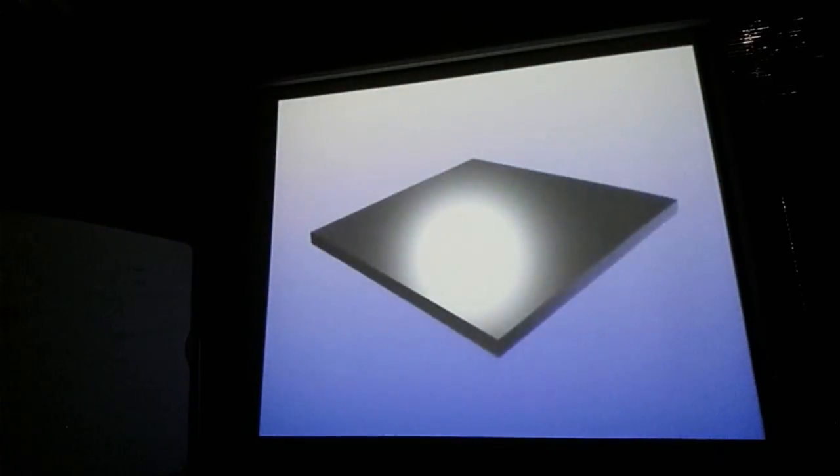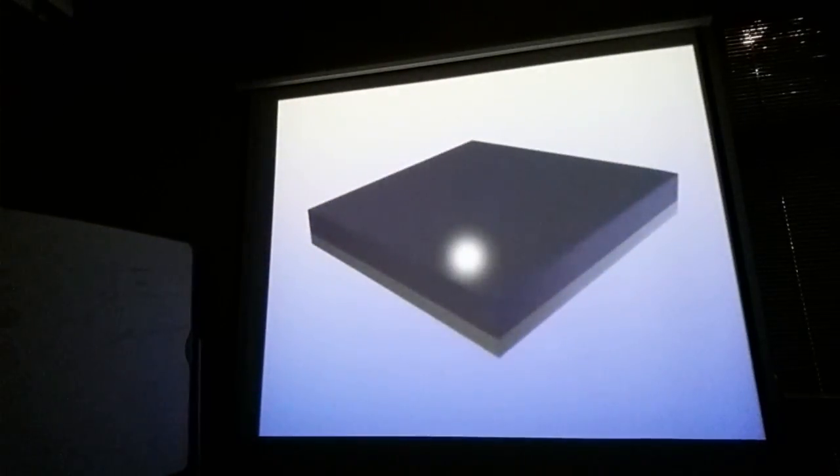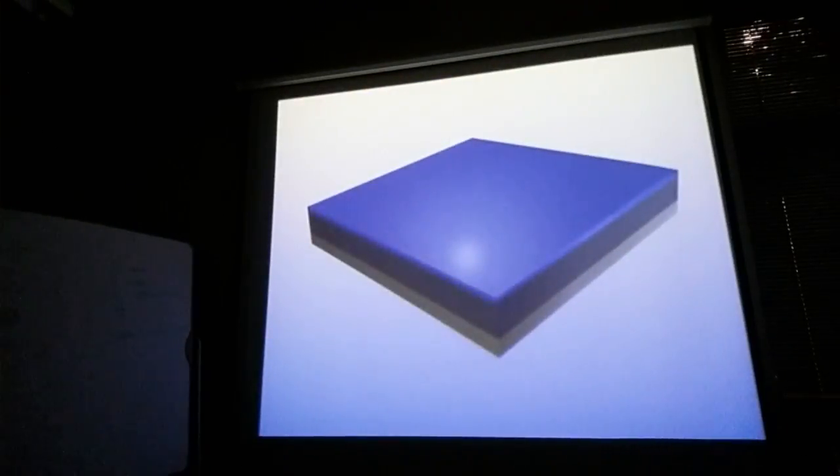Now we have all of the pieces required to construct our silicon solar cell. We start with a metallic layer, which serves as an electrical contact and as a substrate to support the rest of the cell. A thin wafer of boron-doped p-type silicon is laid down. Phosphorus is then diffused into the top surface, forming a p-n junction very near the top. With the p-n junction near the top, most of the sunlight will easily reach the junction. An anti-reflective coating is sprayed on the front surface to cut down on lost reflected light.